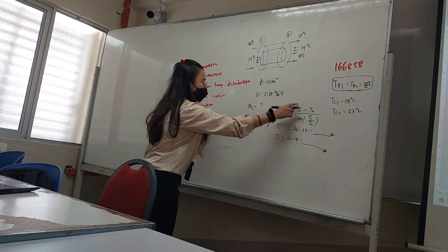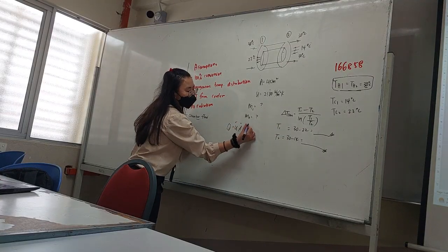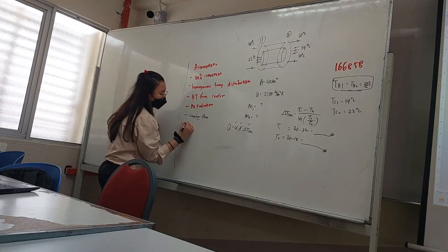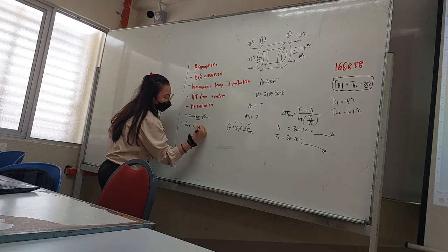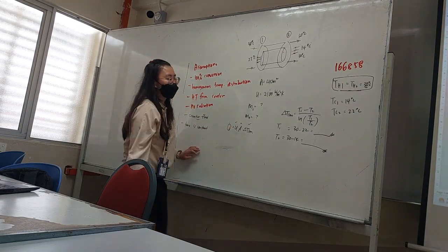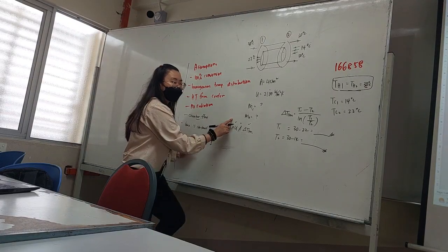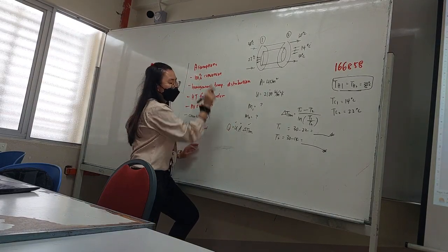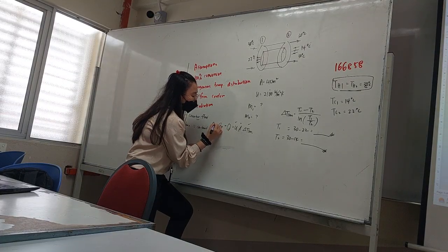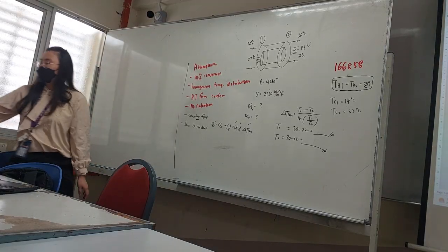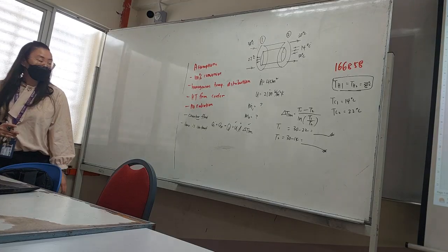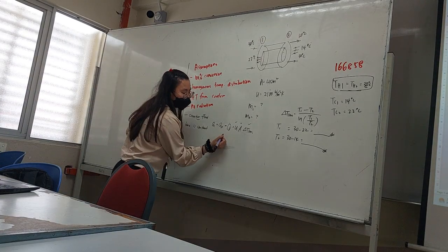Okay, so you start inside. U value known, A value known, delta log mean known, so you know the Q value. Another assumption: because you calculate on the rate, time is constant. So you get the Q value. Because it's 100% conversion, the Q value equals your QH equals QC.